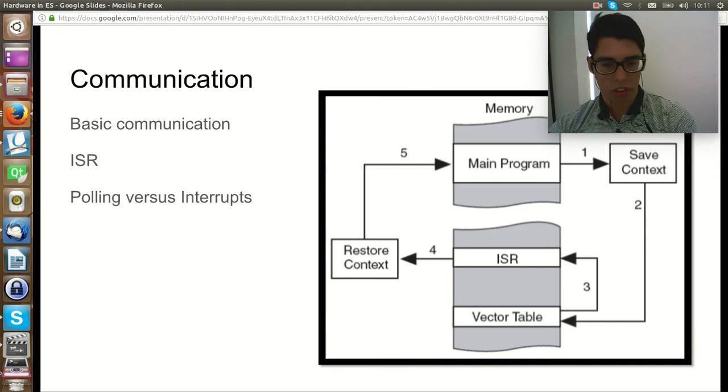It sets the interruption, and it determines which one to select. So the interrupt has the advantage of being more efficient in the use of the processor than polling. The processor can use the idle time for interruptions. Polling is typically used when the processor must respond to events as fast as possible.